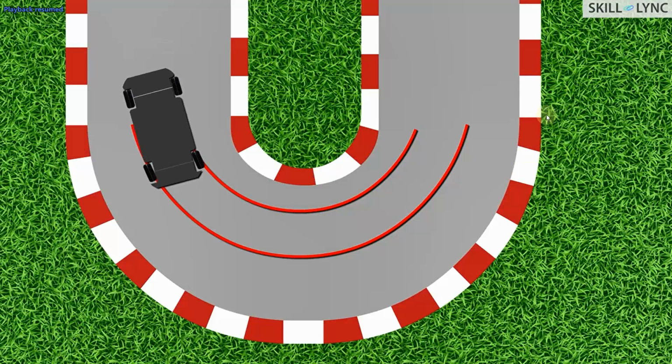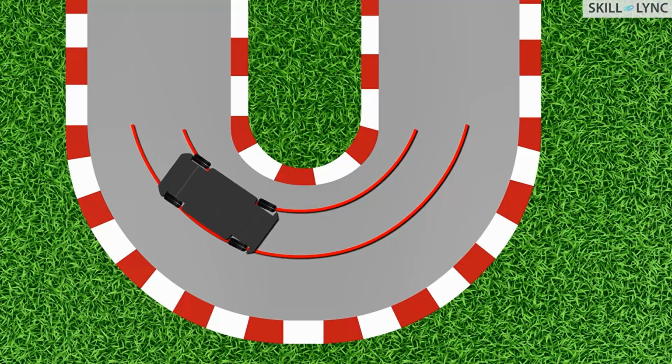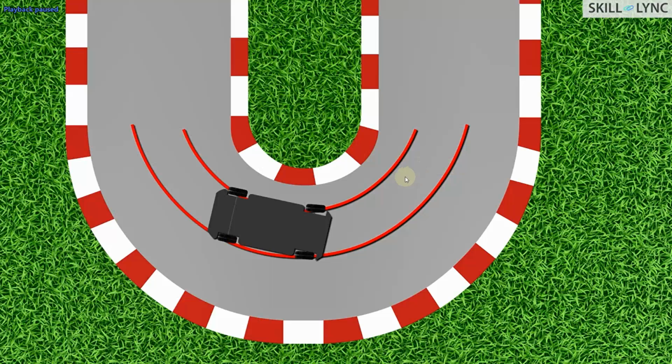While the vehicle is turning, for it to move correctly along this path, you can notice the difference between the angles of the inner wheel and the outer wheel. Both are turning at a different angle. This inner wheel has to turn through a greater angle so that it can undergo this turning correctly.